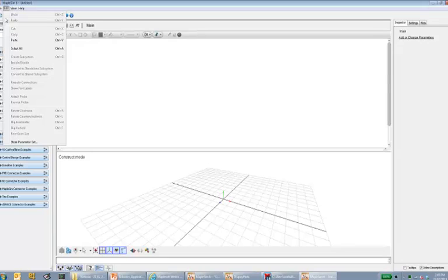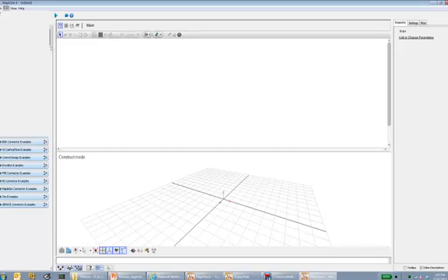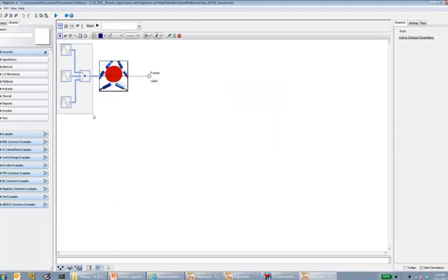So this time we don't have any multibody components. And we'll still have 3 inputs coming in, which are the position of the platform. And what we calculate is the 6 forces for the 6 legs. So the actuation forces required for each leg for the particular trajectory that we decide on for the platform are automatically created within this block. Let's see what's inside it.